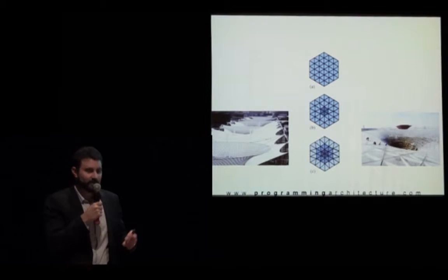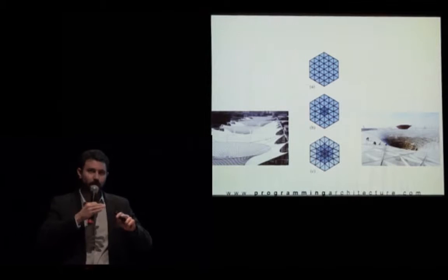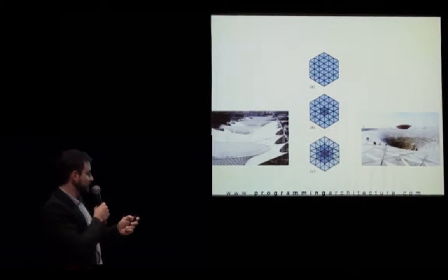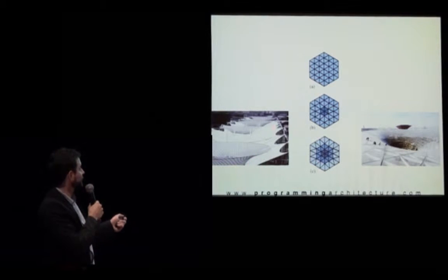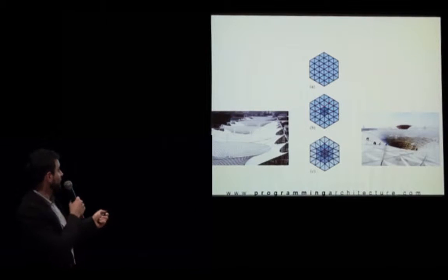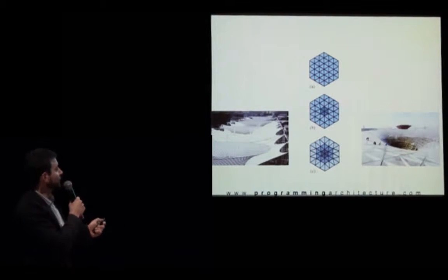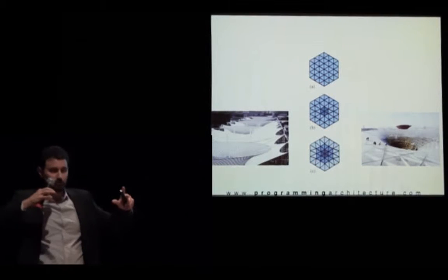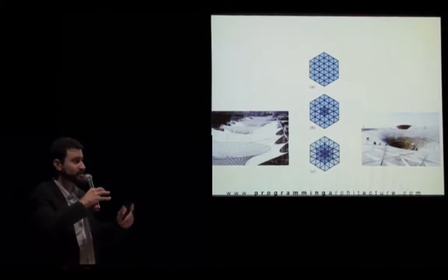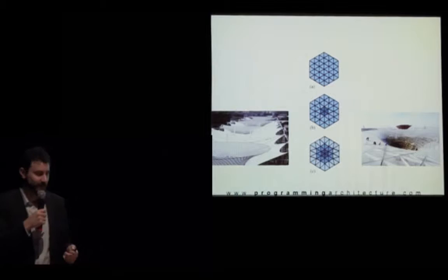With this relaxation process, we could also change the tension in members. So this roof, this membrane roof, which is the largest membrane roof in the world, is connected to these funnels in 3 points. So by changing the tension of members, we were able to pull the mesh toward those points, so we get greater statical stability.